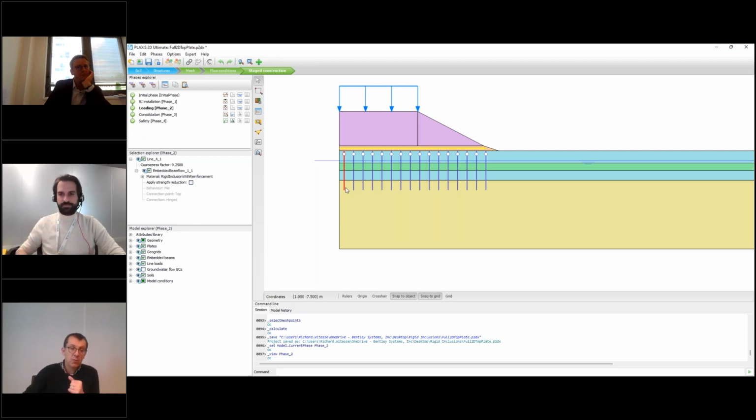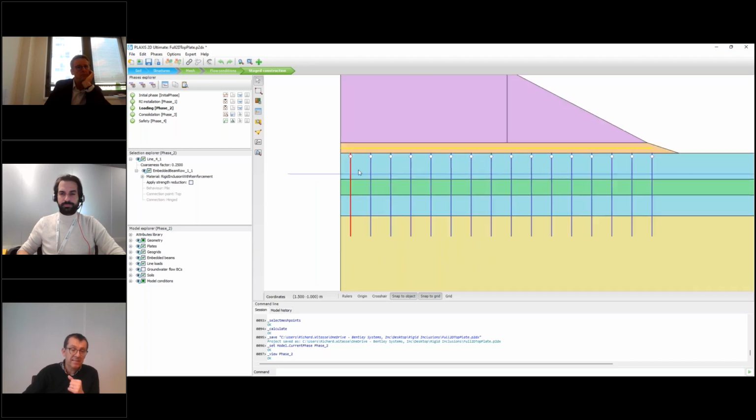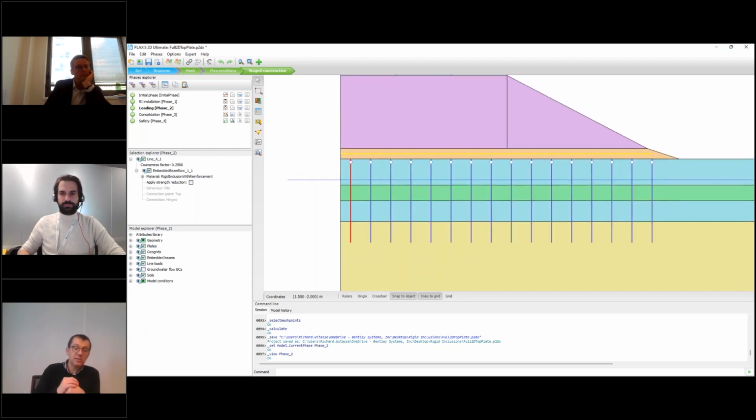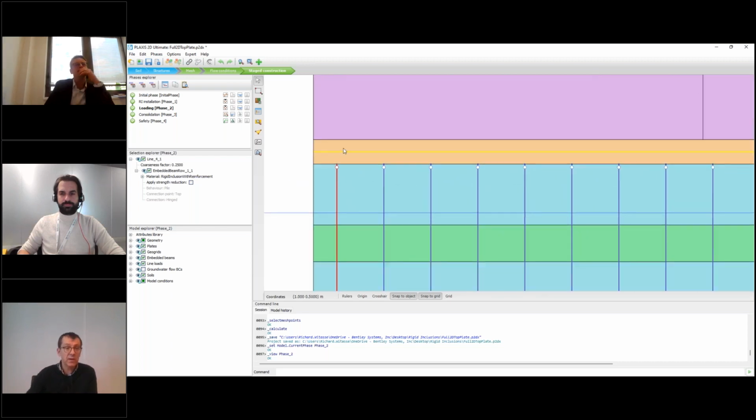Of course, because the exact nature of the soil structure interaction taking place laterally, as well as within the mattress, the load transfer cannot be captured properly in a 2D model. So specific modeling techniques and tricks must be introduced in order to guarantee that the 2D models are still accurate.